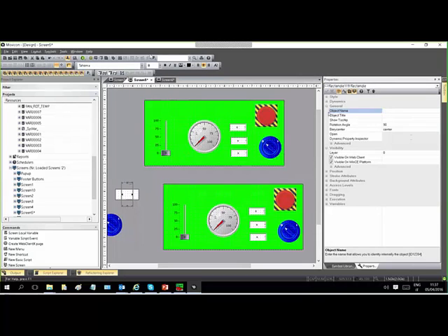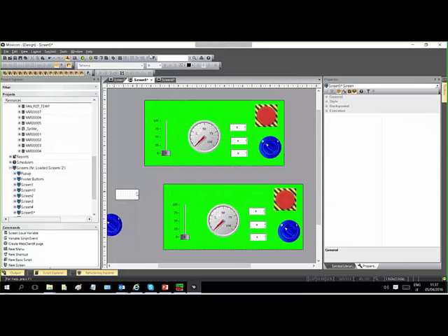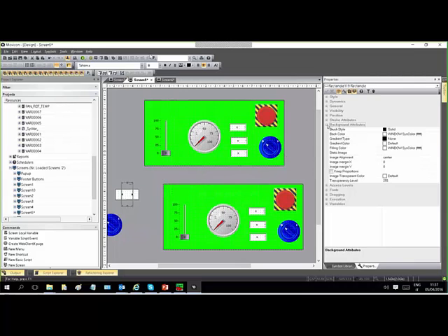Generally also, if you want, you can script. Position is the exact position and the size of the object. Stroke is the text color if you insert a text. Background is the color of the background. Access level is what I showed for the variables, so an object could be under a specific access level, in read or write, visible or writable.